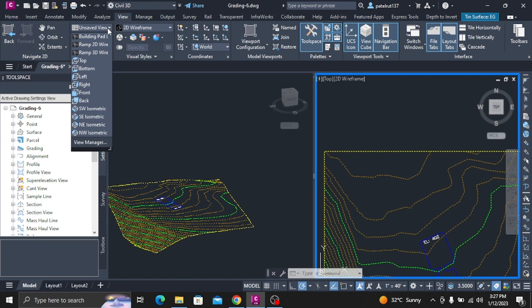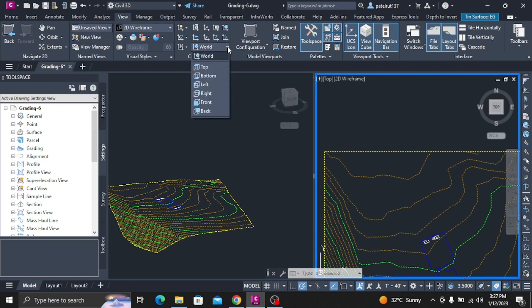Click OK. Now that you have updated the arc tessellation, you must update the grading infill areas to apply the new setting. The easiest way to update the infill areas is by using the AutoCAD Move command. On the command line, enter Move.